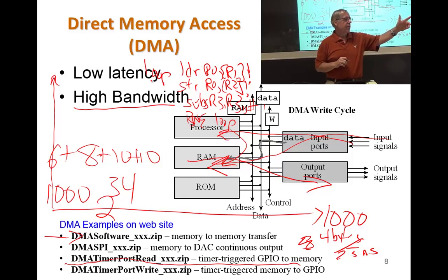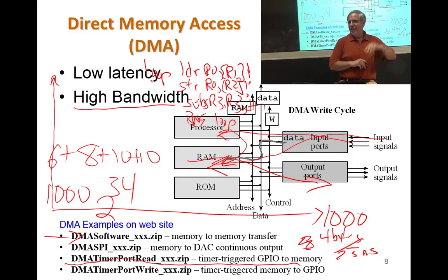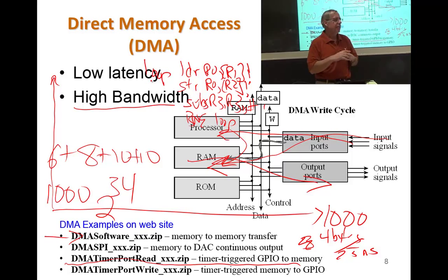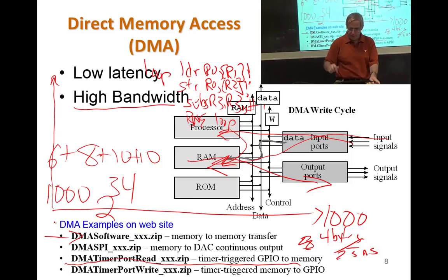Yeah. So there must be like a DMA controller. Oh yeah, he said, how does it happen? There's a DMA controller. And it turns out on many machines, programming the DMA controller is just as complicated as programming the processor. And ours isn't. Ours is pretty simple. You set up the source address, the destination address. Do you want to increment either, or do you want to decrement either, and how many bytes you want to do, and what do you want to do when it's over? It's pretty straightforward. Some starter code if you want to play with it. It's awesome. But we're going to use it to go fast.